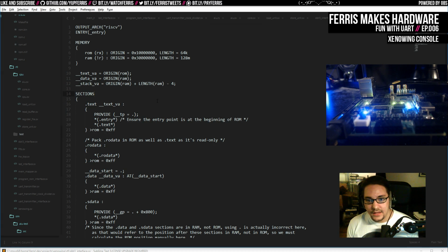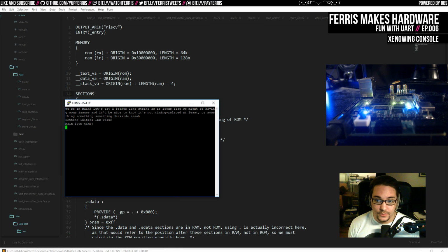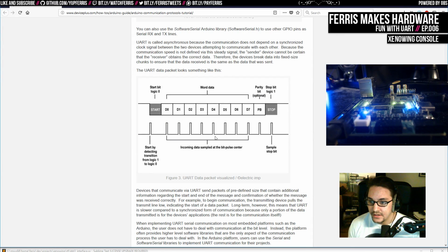And yeah, before we start that, I'll bring over this UART thing again. So I did mention the protocol, and sending that is really easy because you control the timing and everything. When you're receiving, it's a little bit harder because you have to watch for the stop condition, and then you want to read the values at full bit intervals, but with a half bit offset after the start bit.